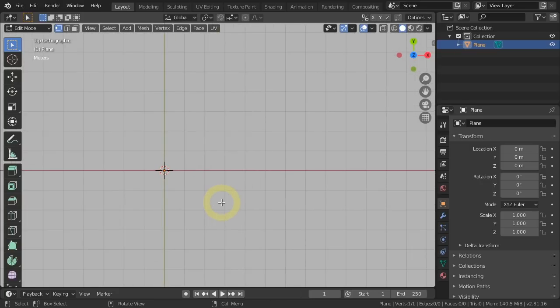Next, let's say you want to create the main road. You can hold Ctrl and then right-click on the location you want to add a new vertex. Just keep doing that until you create the path of the road. Next, let's imagine there is an intersection here. You need to click to select this vertex. Then, just like before, hold Ctrl, then right-click here, and so on to create the road path. Then, for the other side, you need to reselect this vertex again, hold Ctrl, and keep right-clicking to create the path. As you can see, you can quickly build a network of roads and intersections using this method.